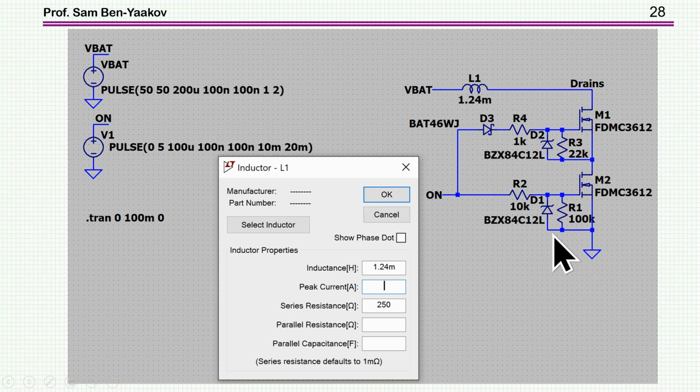So aside from what we've already seen, I've added a resistor here, and here I chose the value of these two gate resistors. Now, the reason for having a resistor at the gate is because you should never leave a gate open, due to two reasons. One reason is that interference and coupling of stray signals might operate the gate if it is open, because the impedance is very high. And another reason is that leakage actually can turn the transistor on. So in case this is open, and I'm just worrying about the case that this line is not connected, in any event, to protect against this situation of a floating gate, I'm putting here two resistors.